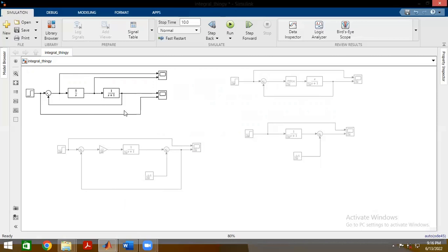If we look at this control system over here, this block diagram, we see that the output is brought back, subtracted from the input, then we get an error term. Meaning this error term is what's being integrated. So if this error function has some sort of finite area underneath it, that is what we'll keep integrating and integrating, and we'll stop integrating it when the area underneath that error term becomes 0, because then that means we have no error.